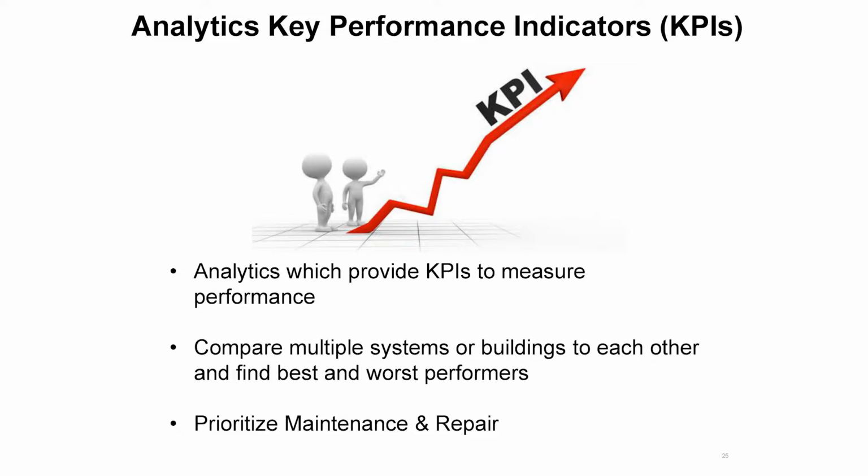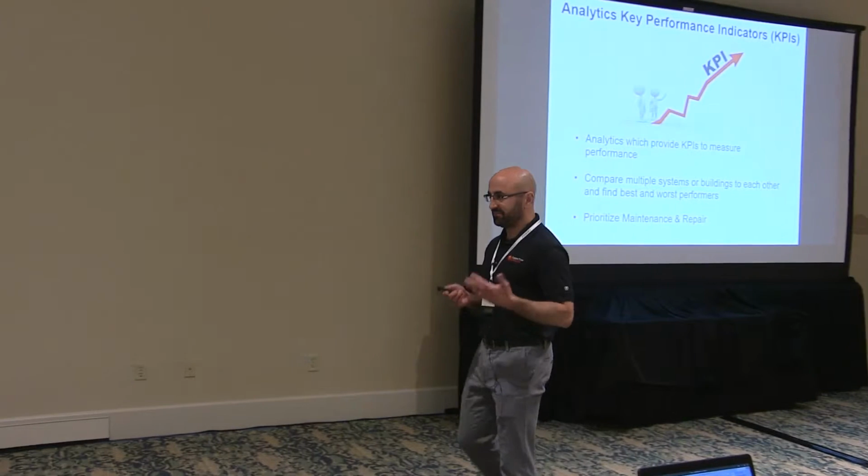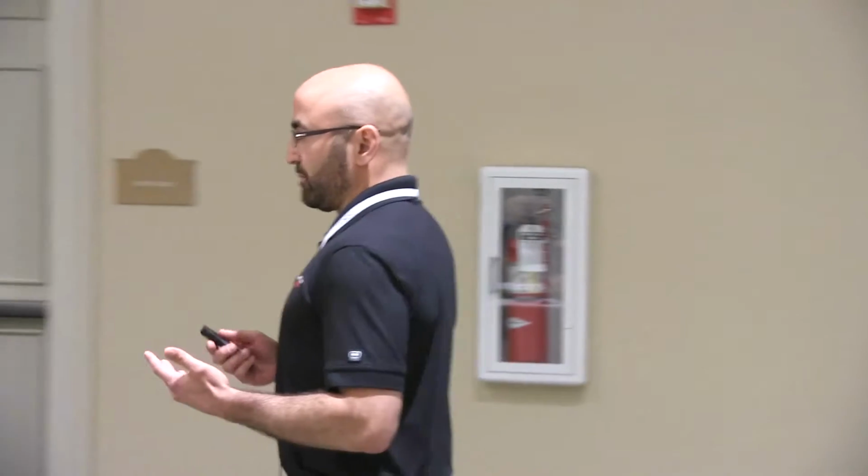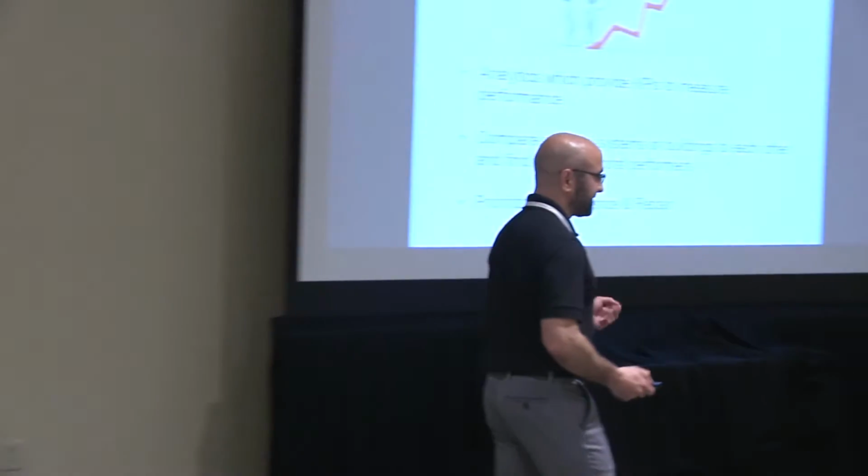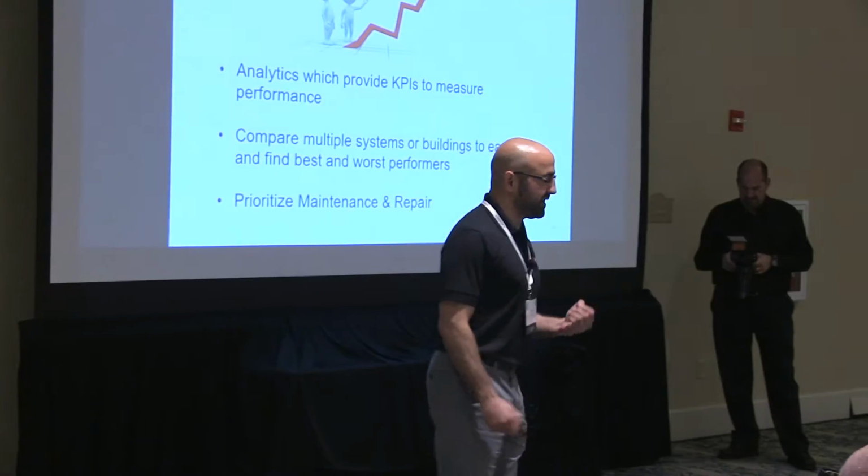You may be going in, doing a combination of physical inspection and data analysis to determine if a VAV is functioning properly. If it's a larger building, you're likely not getting to look at all the VAVs, right? And you're taking your statistically valid sample set, and you're saying, all the VAVs are operating as they should. Well, KPIs can do this in a much better way.